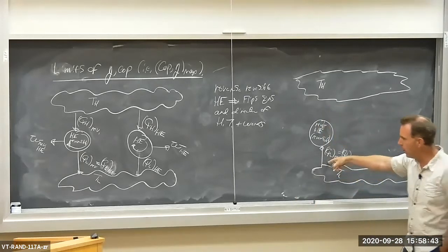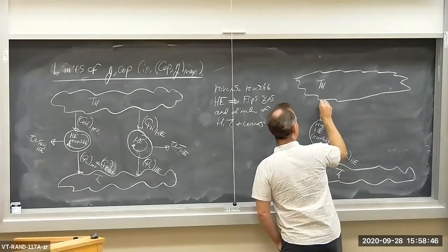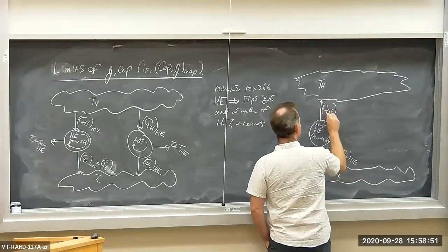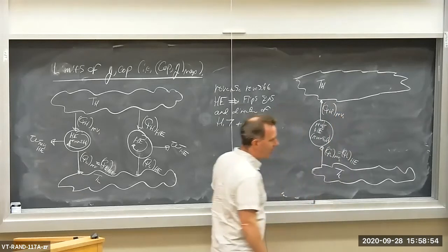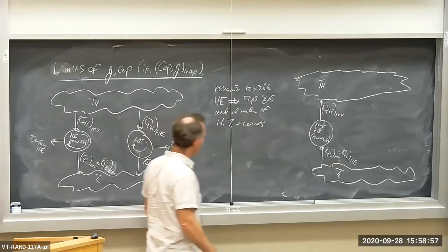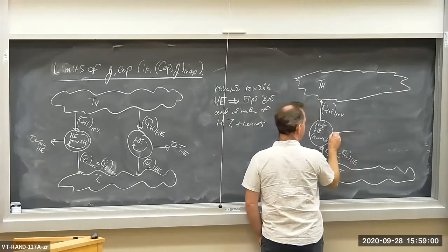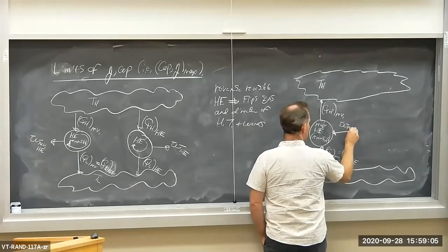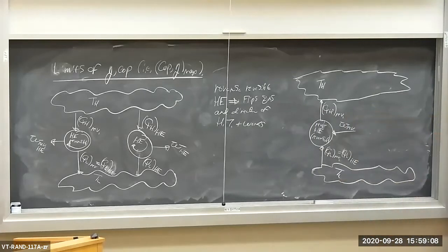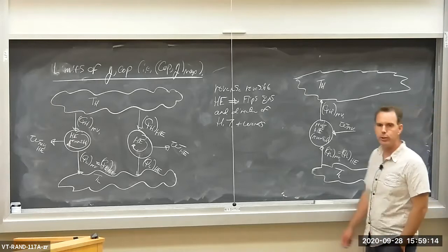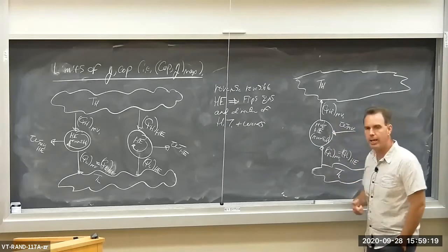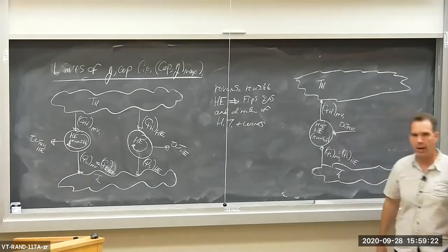It's taking heat from the low temperature reservoir, shoving the heat up to the high temperature reservoir and then some, and is receiving a certain amount of work. Work reversible. Okay? So the thing is a reversed heat engine or a refrigerator or heat pump receiving W reversible to transfer heat QL from the low temp to the high temperature reservoir.